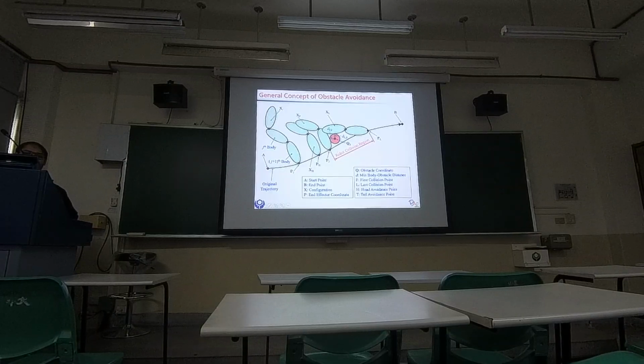Then there is the heading point where this collision will start. We make a point before the collision point, which we name the obstacle avoidance head point, which starts the avoidance from there. So here is the obstacle avoidance head point, and there is a distance between the head point and the obstacle.